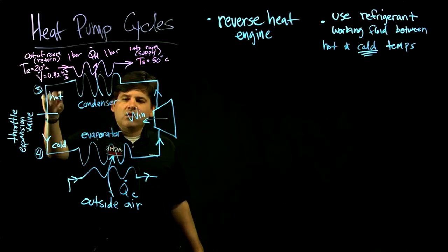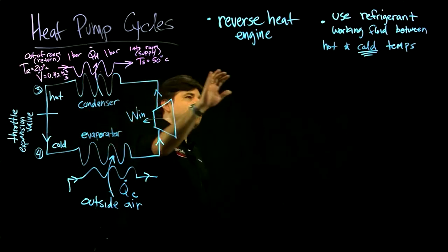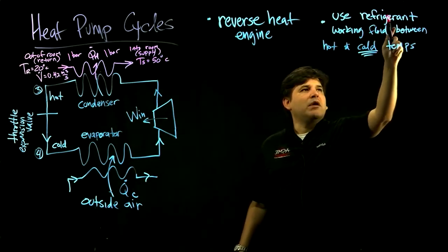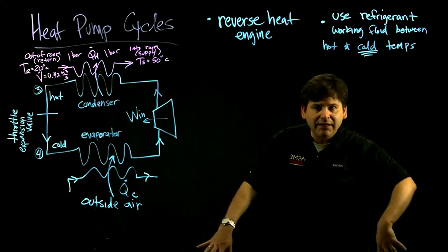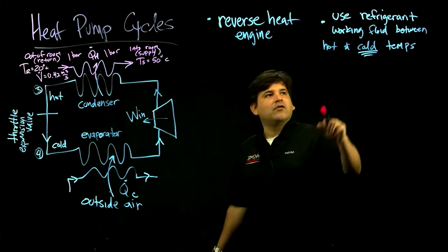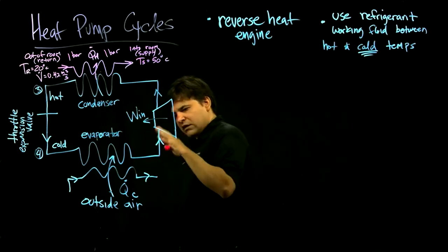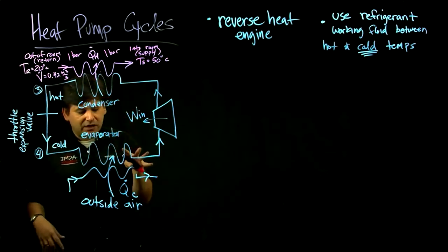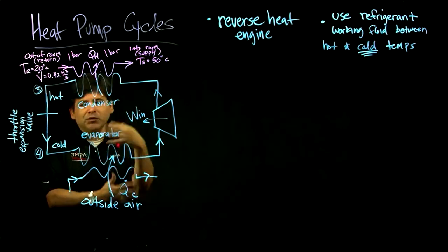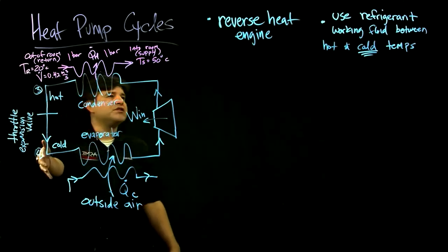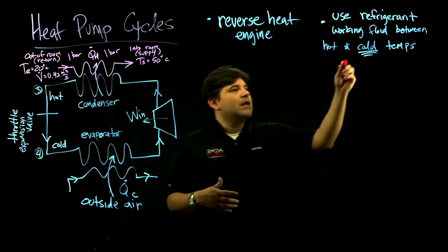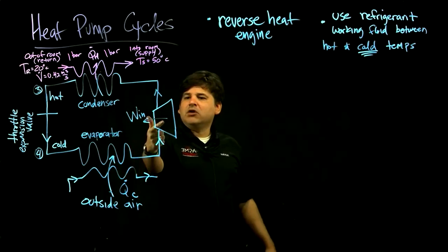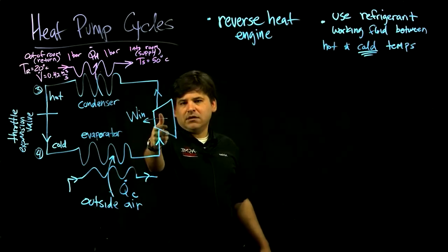The way that these are designed is you need a special molecule to work efficiently, that when you expose it to high pressure and then expand it in a quick valve, just almost like a spray nozzle. You just have a high pressure on one side, then you push it through to lower pressure. And if you do this to the right molecules, it'll get very cold, and you don't have to put a lot of work in, depending on the molecule.